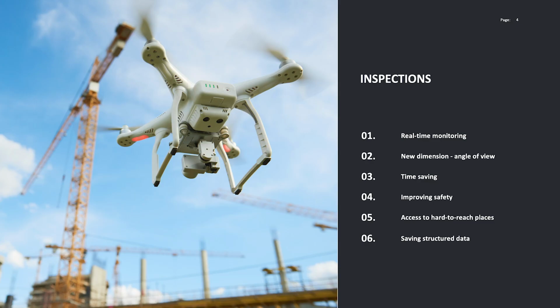Also, it gives you a new dimension. If you are going on a visual inspection, first of all, you look with your eyes, and mainly you can take pictures or videos. With the drone you get this new dimension, because you get the view from above, but you can also go all the way around. In many industries and types of facilities, this opens a view they haven't seen, or not every day, because the access is hard.